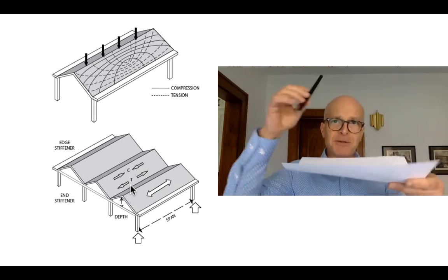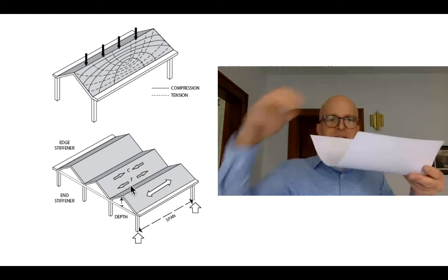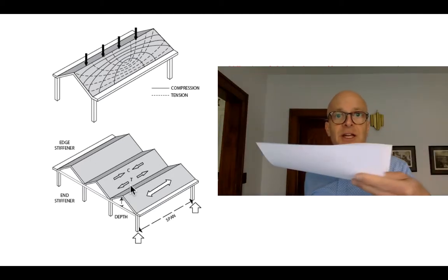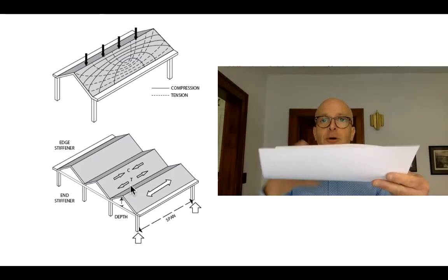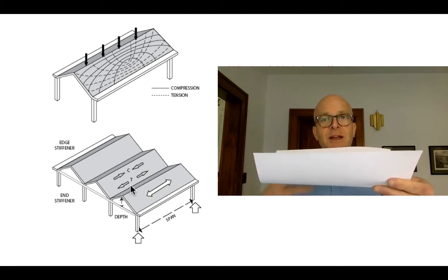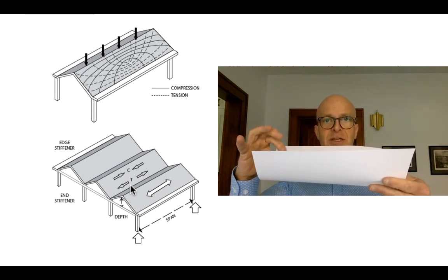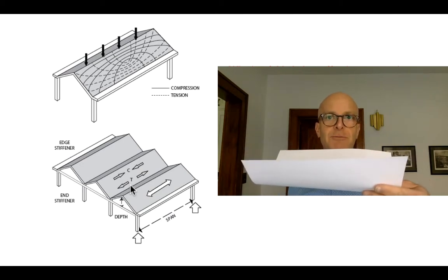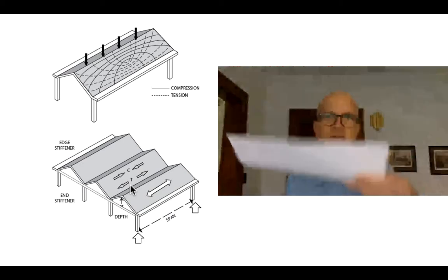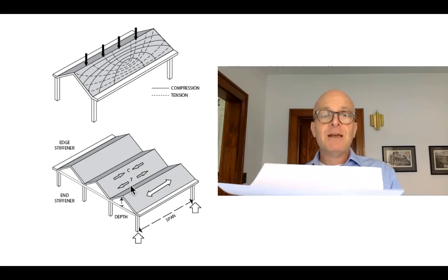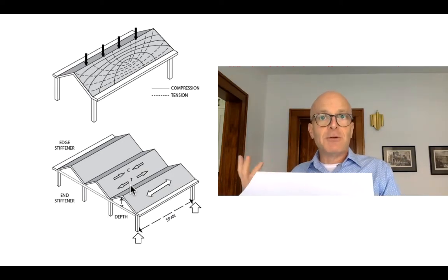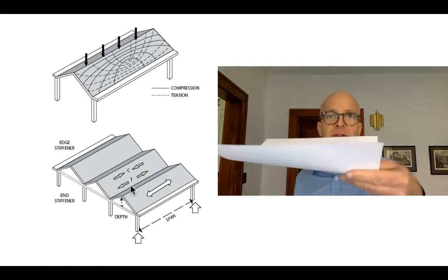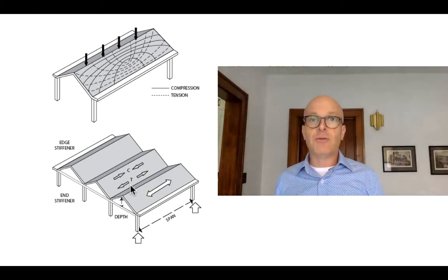And if I take my test weight here, you can see that the folded plate is going to carry that pen. The paper has gone into bending, not across its thickness, but instead across the depth of the fold that I've given to it. Right? This is the simplest folded plate imaginable. Notice though that I'm having to do a little bit of work. My fingers and thumb are forcing the paper to hold that shape.